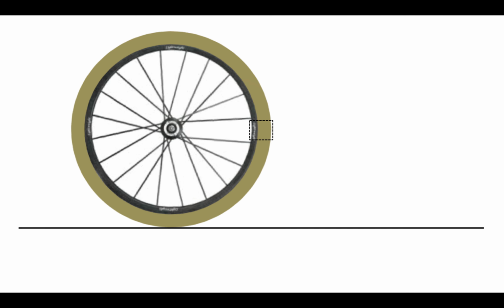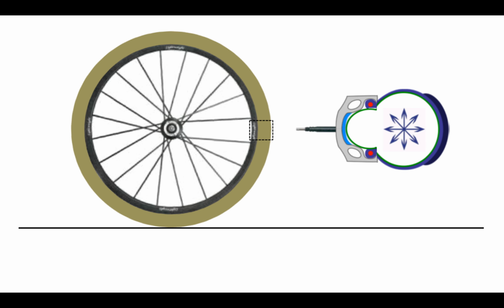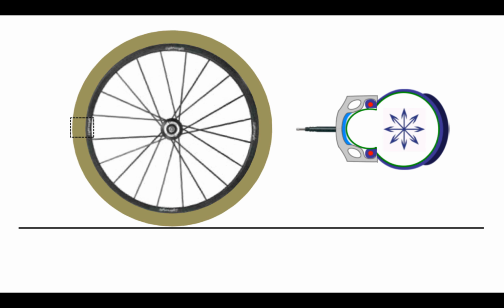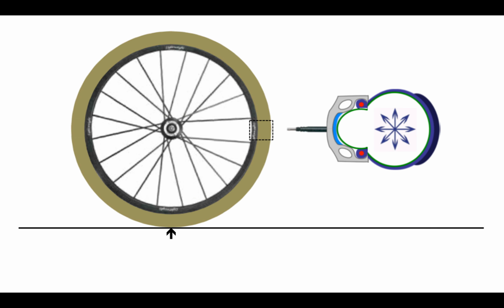Let's imagine our wheel and tire, and if you look at the 3 o'clock position, you'll see a rectangle, and let's say that we're looking at the rim, tire, and tube combination at that point. We want to see what happens to the shape of the tire and tube as the wheel rotates clockwise 1/2 turn, and as it does, the tire and tube go through the load-bearing zone. We can visualize this.